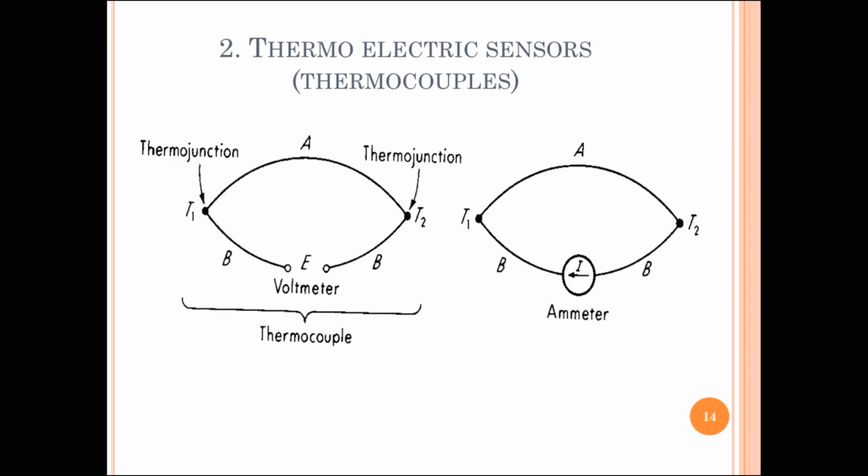Actually, the thermoelectric EMF is an effect uniformly distributed along the length of each single metal wire, and it exists even if the wire is not connected to anything. Its magnitude depends on the material property called absolute Seebeck coefficient and the distribution of temperature along the wire.